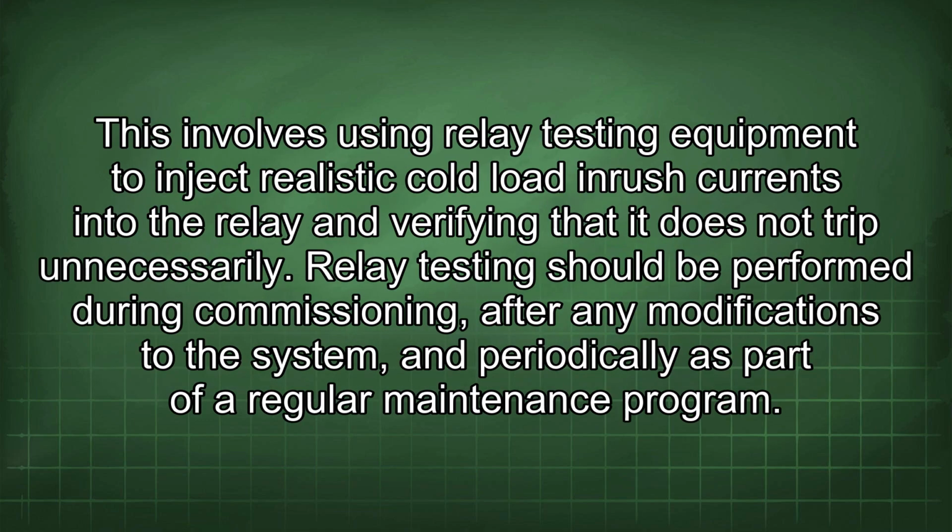Furthermore, it is crucial to perform thorough testing of protective relays under simulated cold load conditions. This involves using relay testing equipment to inject realistic cold load inrush currents into the relay and verifying that it does not trip unnecessarily. Relay testing should be performed during commissioning, after any modifications to the system, and periodically as part of a regular maintenance program.